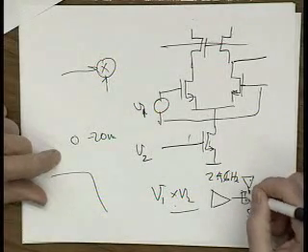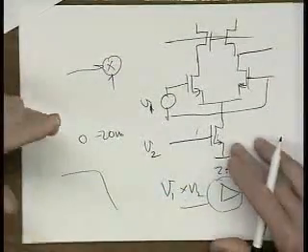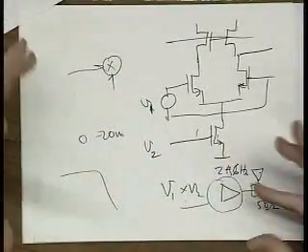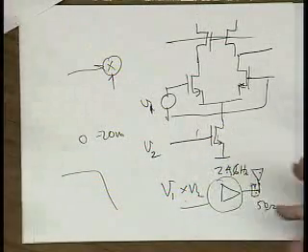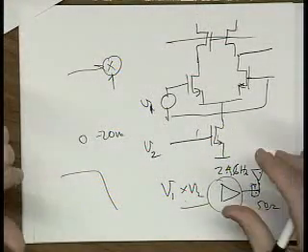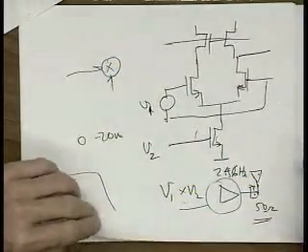So how do you do this power amp? I'll show you, but you guys know it. It'll be very similar to circuits you've seen so far. You can use inductors to tune out capacitance as much as you possibly can, but you still end up basically having to drive 50 ohms, and you know how tough that is, right?